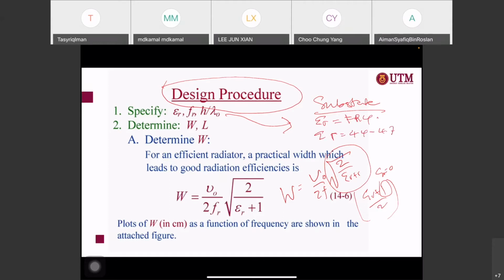The problem for FR4 is in terms of this particular dielectric substrate here, because the dielectric constant is not constant. It's not constant. So that's why with FR4, sometimes if you design, you can have different values from your simulation because the epsilon r is not the same.